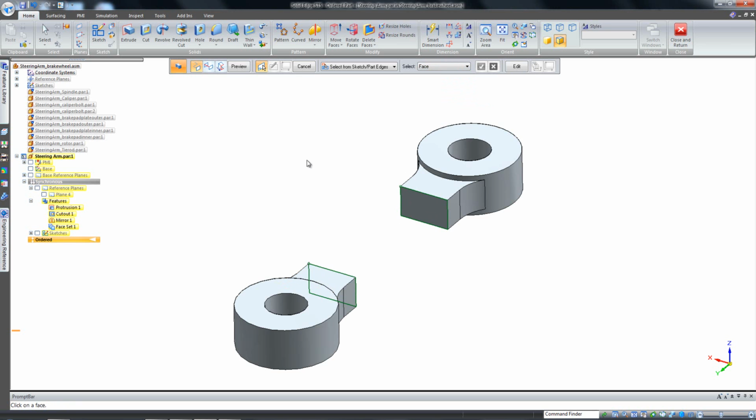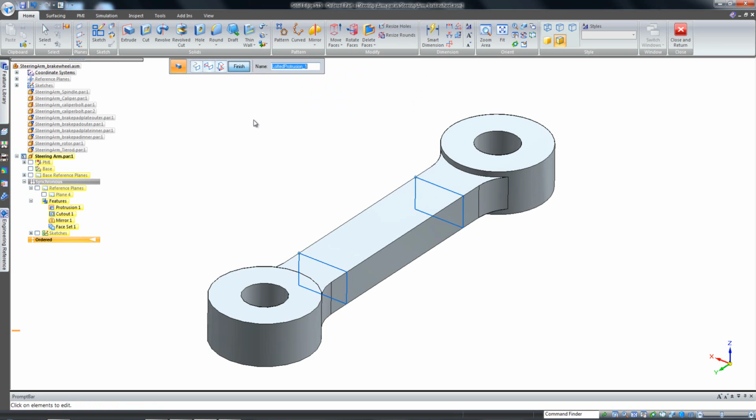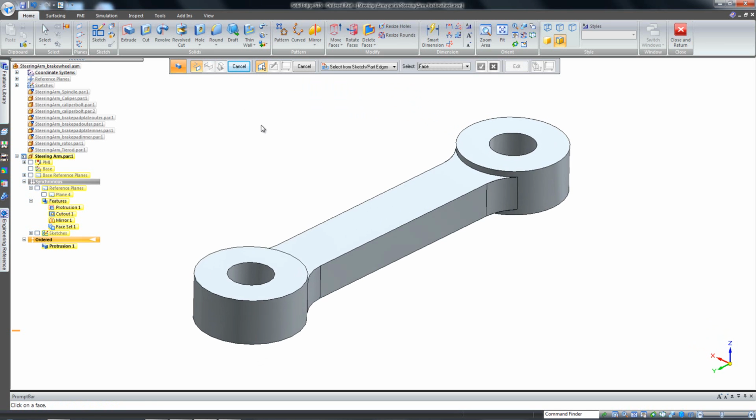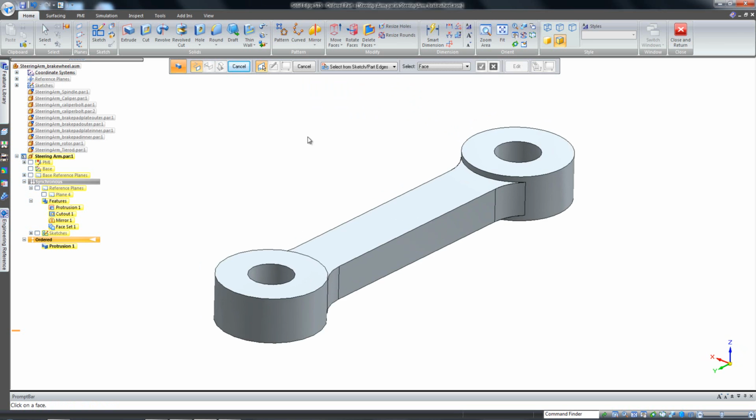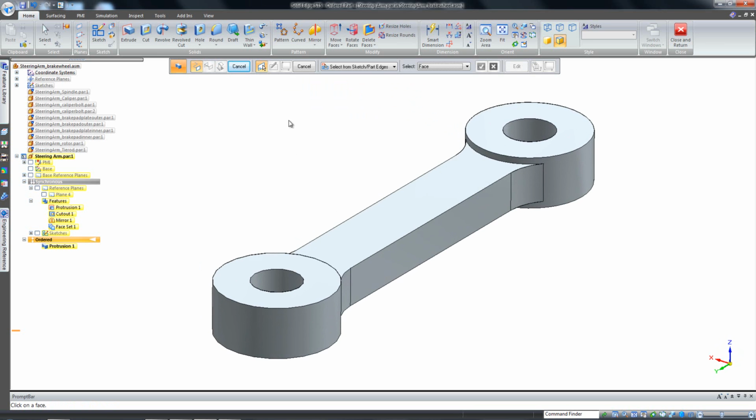Before I finish out that particular operation, I also want to tell Solid Edge that I always want them to come out tangent from those two locations. So we'll change those two to tangent continuous and complete that step. And that gives us the middle portion of our body. And you'll see why that tangent continuous comes into play a little bit later, why that's important.